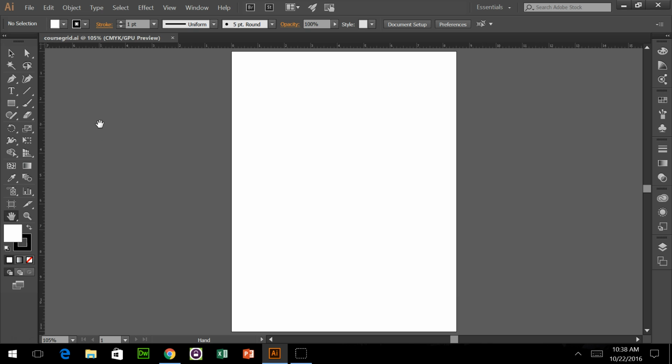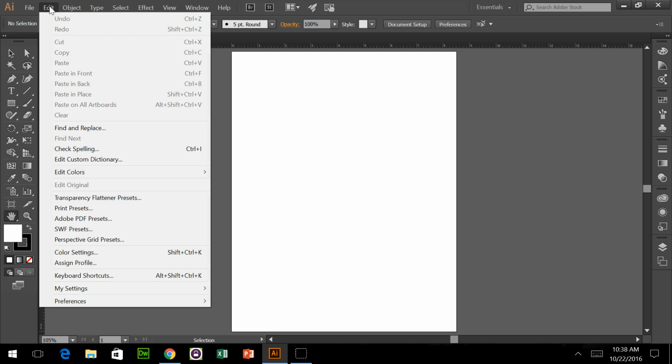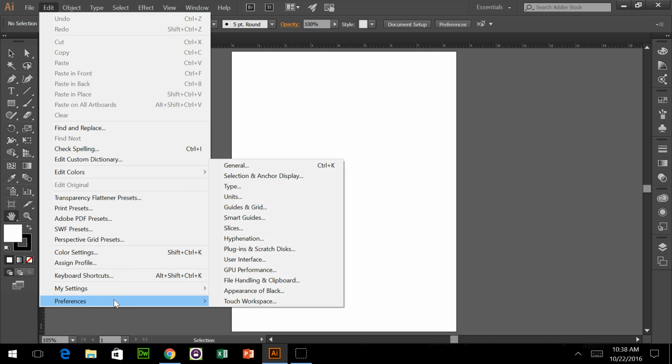Next thing I'm going to do is I'm going to do some setup, and this is what this first video is going to be about, is just setting up your page to get it ready to draw on. First thing I want to do is I want to put a non-printing grid in the background of my page. So I'm going to say Edit, Preferences, and I'm going to go here to Guides and Grid and click on that.